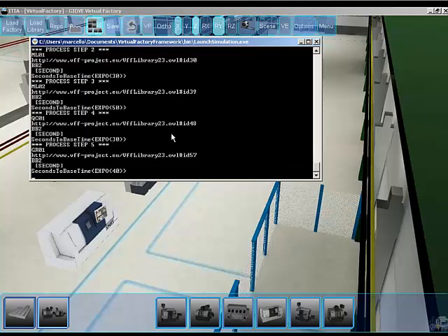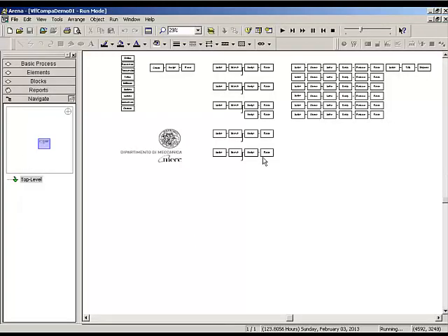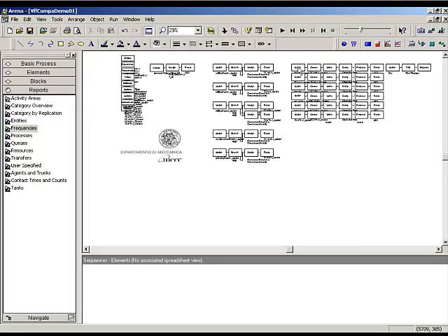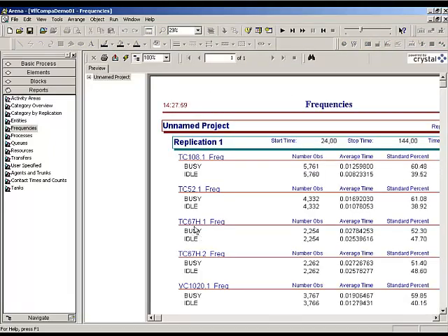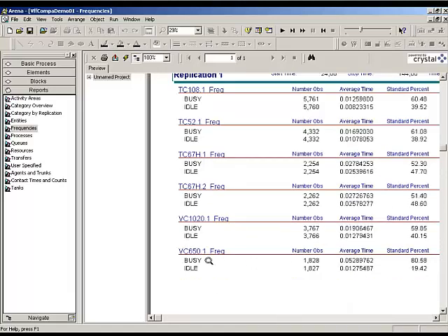my tool that is looking again into the system and is launching again the simulation, and now we finish. If you look here, you will see that we had 6 stations instead of 5, so it was able to realize that a modification in the production system was done and is able to evaluate how the new system behaves. Now, if I look at how the system behaves, I see that I have 2 machines of these types. They are not completely saturated anymore, while the most saturated machine is the last one.